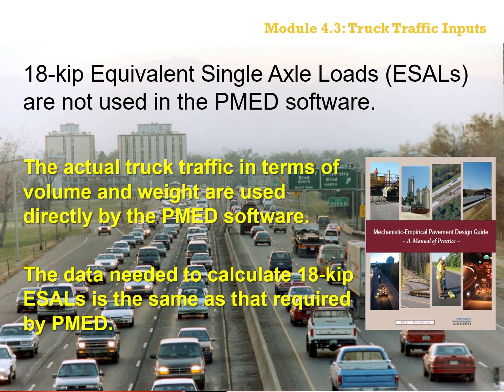The introduction to the traffic data is to reinforce the data required as input variables to the MEPDG-based procedures and is no different than the factors needed and used to calculate the number of 18 kip equivalent single axle loads for the empirical AASHTO design procedure as well as other mechanistic-empirical based procedures.